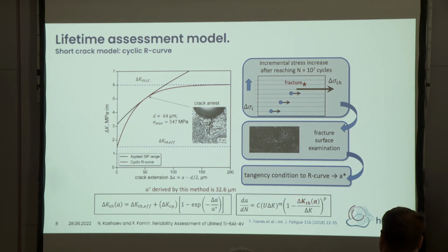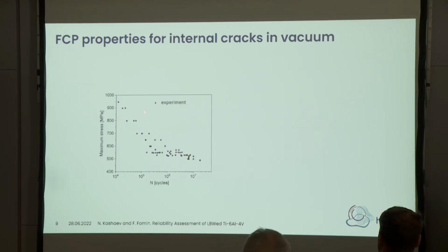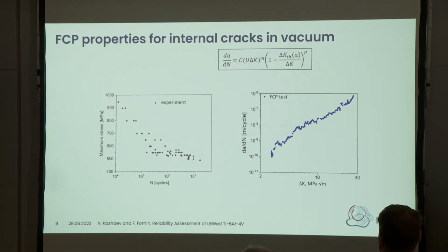And then we can integrate this behavior, for example, into the NASGRO equation, where the near threshold behavior can be considered. And now, in principle, we can calculate fatigue properties. Here are the results of our experiments, the behavior of specimens with the welds.